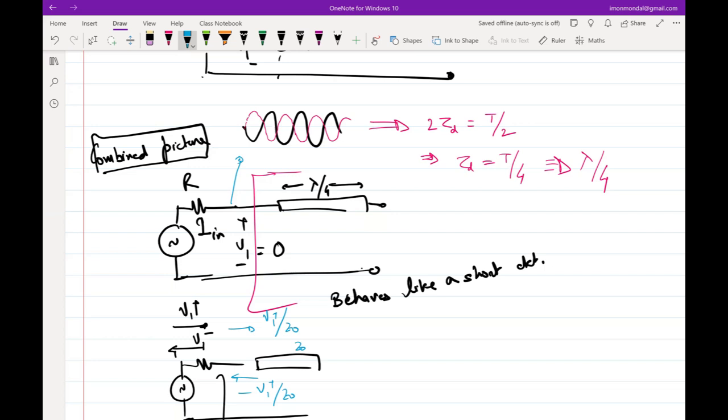Okay, so this type of application is regularly used when you have power amplifiers plus an LNA on a single chip. Typically, in most cases power amplifiers are kept on a different chip. But if you have a power amplifier and an LNA on a single chip, and the power amplifier output, which is at a much higher voltage or power level, is at a sufficiently different frequency than the LNA, then you can put this lambda by 4 transmission line open circuit and notch it out. And that is also done.